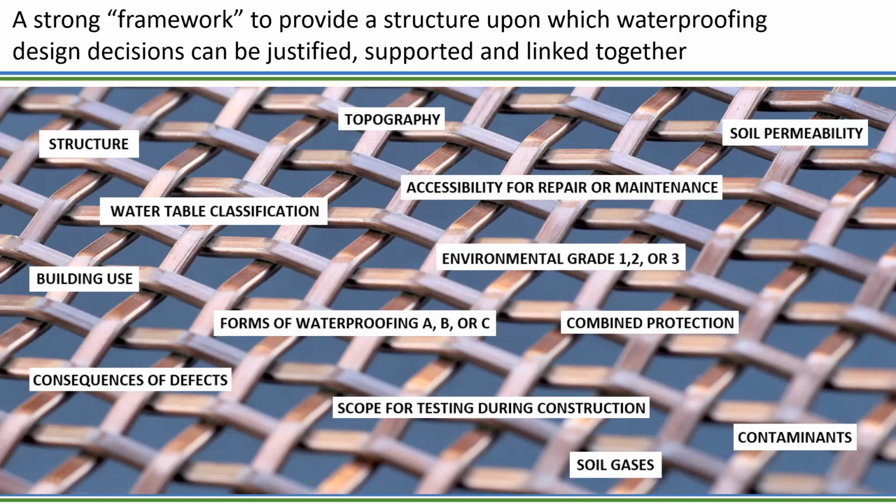Can we test waterproofing systems during construction? Generally, no, because we can't flood the site for a couple of weeks while we all wait to see if the basement's going to leak before we backfill it. So that can lead to the choice of combined systems to reduce risk, etc. We'll come on to all of these in a bit more detail.